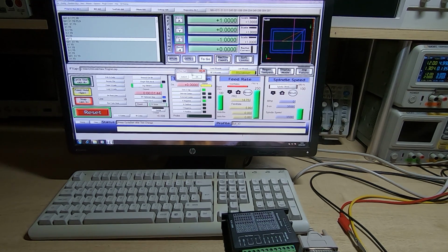I mean, you may have zeroed the first tool on the top of the stock material, but you may now have machined that away. For example, if you're doing a roughing cycle with the first tool and you want a finishing cycle with the second tool, you might find the top surface that you originally zeroed to is now no longer in existence because it's now bits of swarf all over your workshop floor.